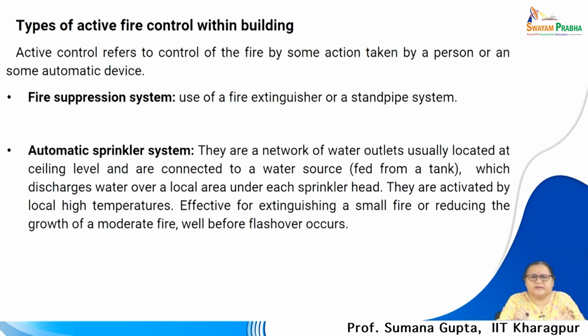However, in larger buildings or higher buildings, it is mandated that you have to have a standpipe system. Now, we will discuss the standpipe system. Other than that, we can have an automatic sprinkler system. This standpipe system can also support the sprinkler system. The sprinkler system can be independently fed by water for control of fire at the point where it has started.